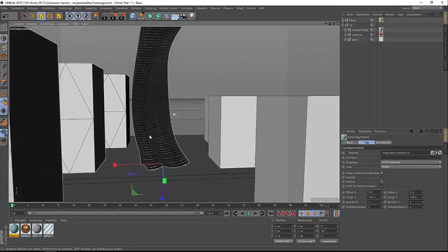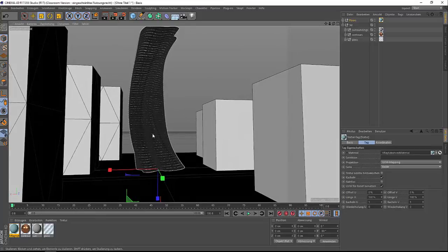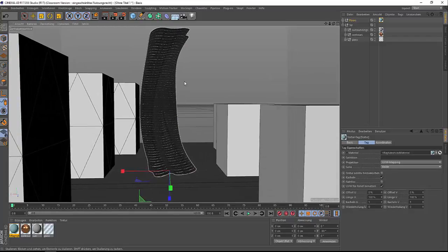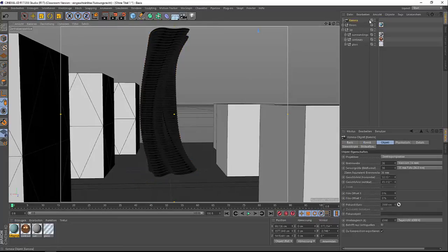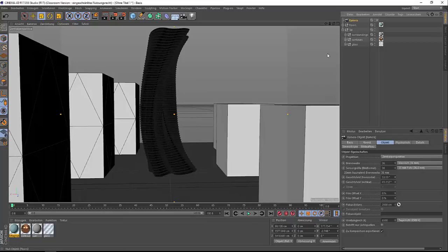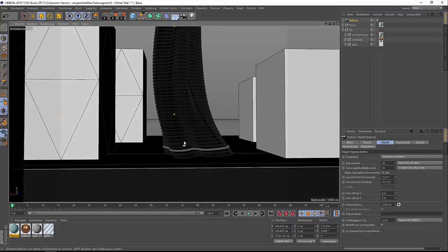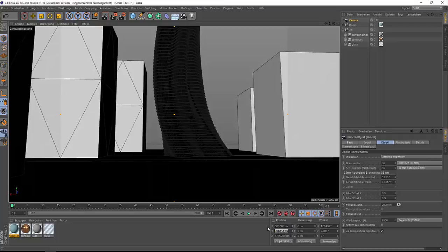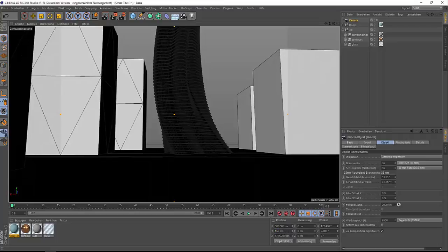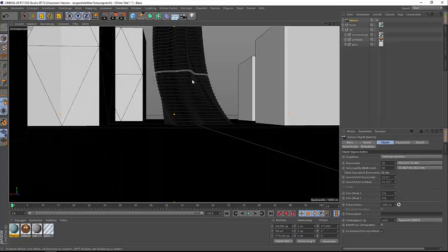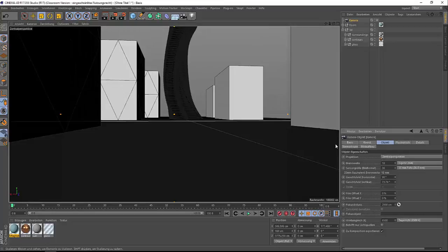Now what we want is creating a camera as well as a light system and simply render. It's a super easy task to do. So I create a camera, I click here to go inside my camera, and I position this camera at human eye, so 160. Now I want to make sure that my camera is straight, and since the building is huge, I want to go inside my angle and change this to something like, say, 18, so that now I have a better view.